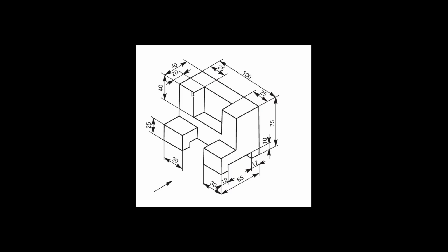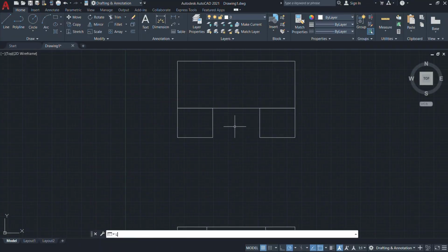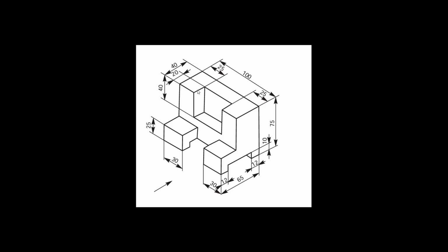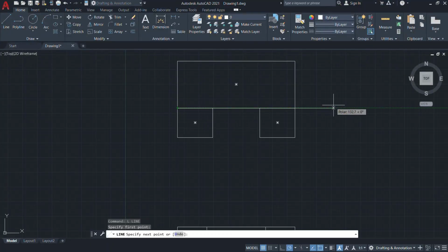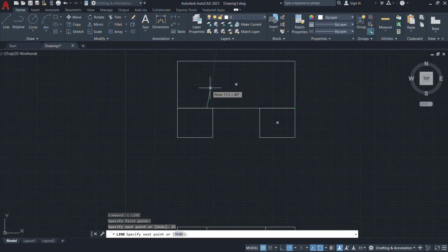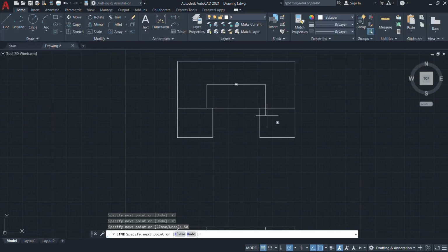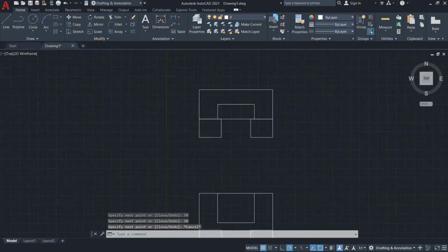Now, once we draw our two opposite rectangular profiles, let's indicate the pocket portions. The top pocket portion is clearly indicated in visible lines itself. So using a line profile, the horizontal dimension is nothing but 25 mm. So mention 25 mm horizontally. Again, draw one vertical line. It is just to represent a visible edge with a distance of 20 mm. Then the horizontal line is 50 mm, that is the pocket portion. Again, the vertical line is 20 mm. So mention 20 mm on these areas.